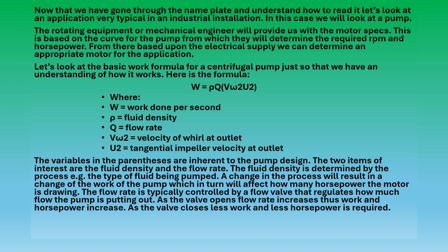So let's look at the basic work formula for a centrifugal pump, just so that we have an understanding of how this works. Here's the formula, which is work is equal to density times flow rate times velocity of whirl at output times tangential impeller velocity at outlet. So the variables in the parentheses are inherent to the pump design. When he specs out the pump, it's going to give you these values.